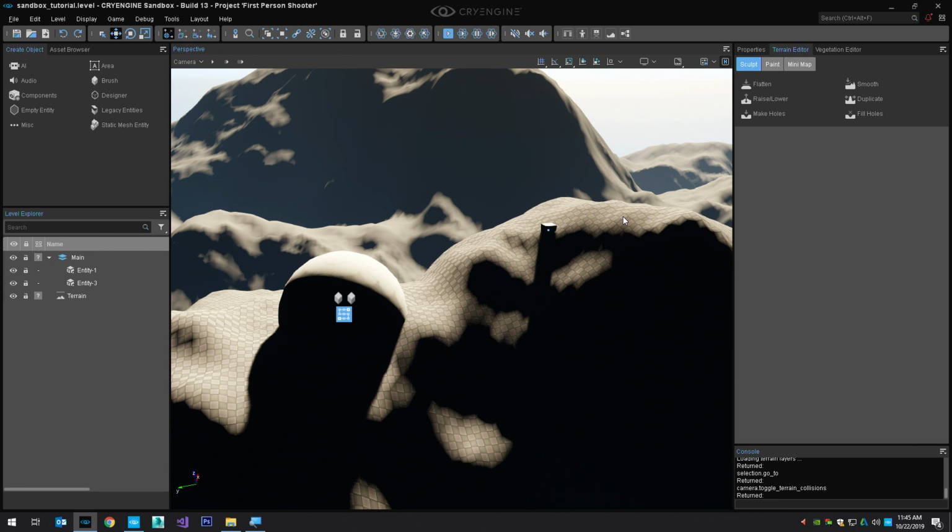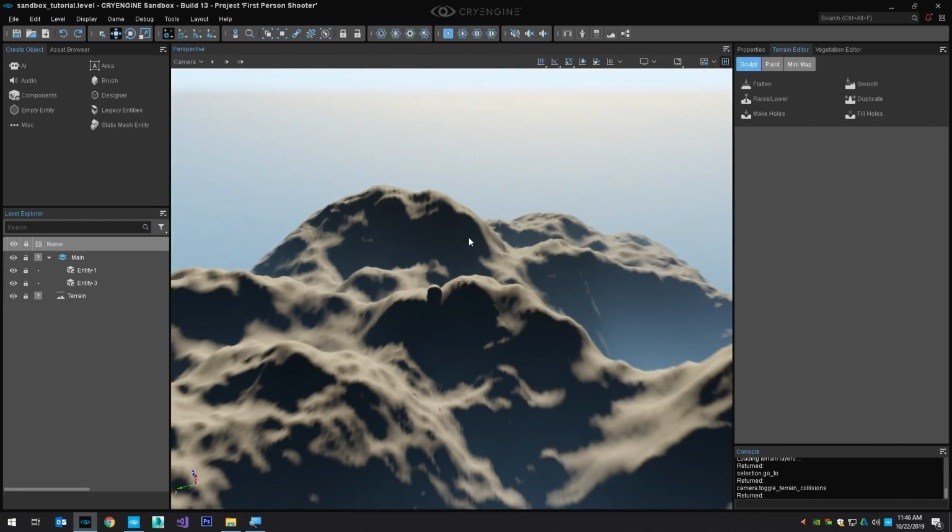an important lighting thing. One of the basic things you're going to do is make the lighting more real. Do you see how the shadows are black? There are two ways to address this. One is to use ray tracing, which we call SVOGI in our system, one bounce ray tracing, but it's expensive. One of the things you want to do that's more basic is use some ambient light, some indirect lighting, okay? And we do that through what's called an environment probe.